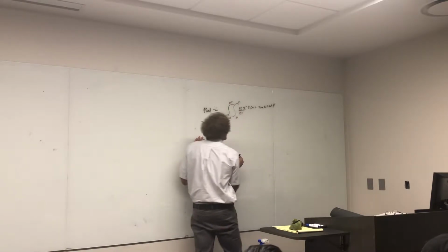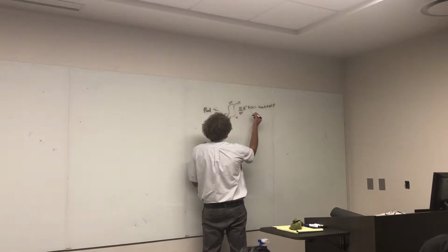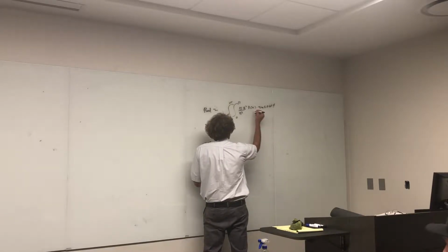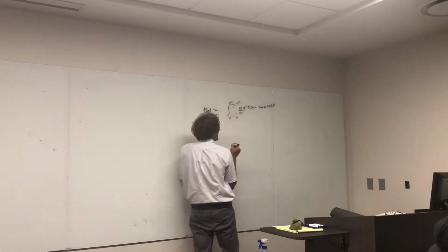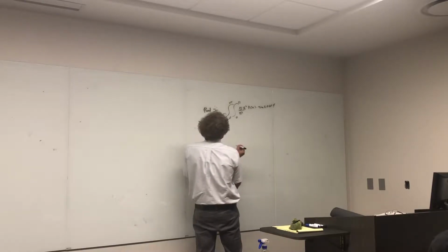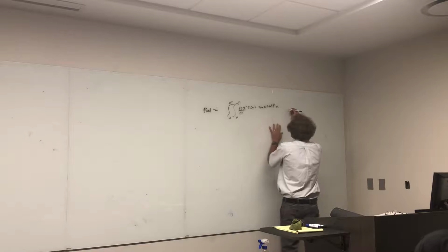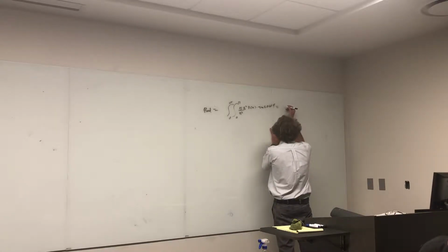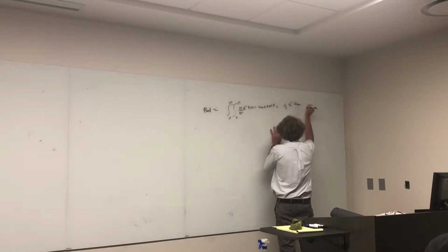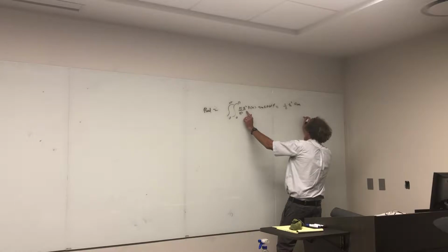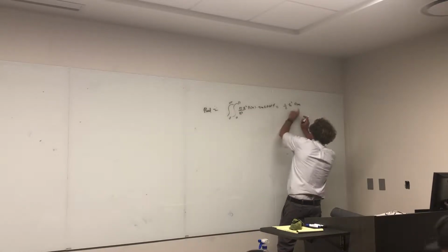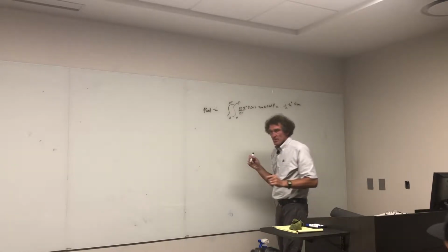One thing you're going to see is that if I did this right, I could divide that by F max and take F max outside, and then I could use the normalized power density. The power radiated would be equal to that, and that would be equal to simply 1/2 I naught squared times R rad. So the I naught squareds would cancel. You could take twice that and get R rad if you wanted to. Do you follow me on this?